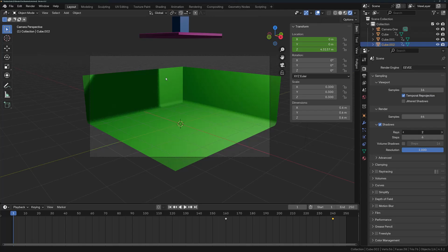But it is going to increase the overall quality of that specific part of the scene. So in this case, we increase the number of rays generated, and that's going to increase the shadow quality. There are many other options here, but for now, let's just preview what we've got in our 3D viewport.